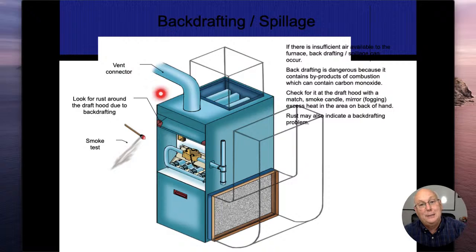If there's a blockage in this vent connector, if it has a thermal barrier somewhere in the chimney, then I'm going to start backdrafting. Now with these, I am going to tell you that backdrafting is normal. All right. When they first start up, you are going to backdraft until it gets built up enough heat to get that draft and get it started.